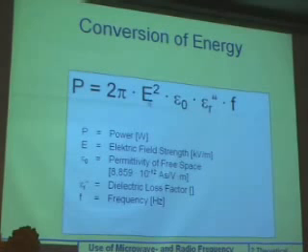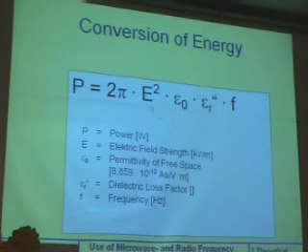You get lightning, and in consequence of the lightning, the product burns. So you have to be very careful in changing this, but this is quite easy. The bigger the cavity, the lower the electrical field strength, and if you have a big cavity, nothing can happen. Therefore, if you buy a microwave oven, please buy one with a high volume, then you get a low electric field strength and a very homogeneous field. A small one is more difficult.